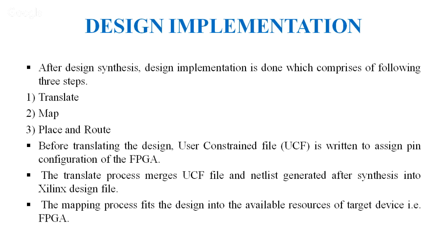Design implementation has three steps: first translate, then map, and then place and route. Before translating the design, the UCF file is written to assign the pin configuration, as I told. The first step is translate. What does this step do? It merges your UCF file and the netlist generated in the synthesis process into a Xilinx design file.